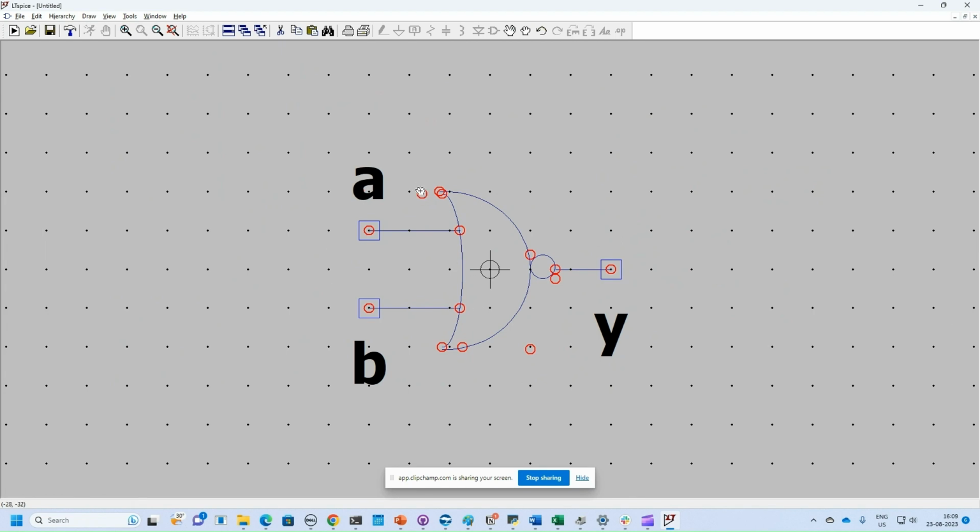So these are called the anchor points. The way we do that is you select drag again, select the anchor point, and then move the anchor point. It will adjust the shape of the symbol. You can try this with different anchor points, and figure out how to change the shape of the symbols that you have created. Okay, thank you.